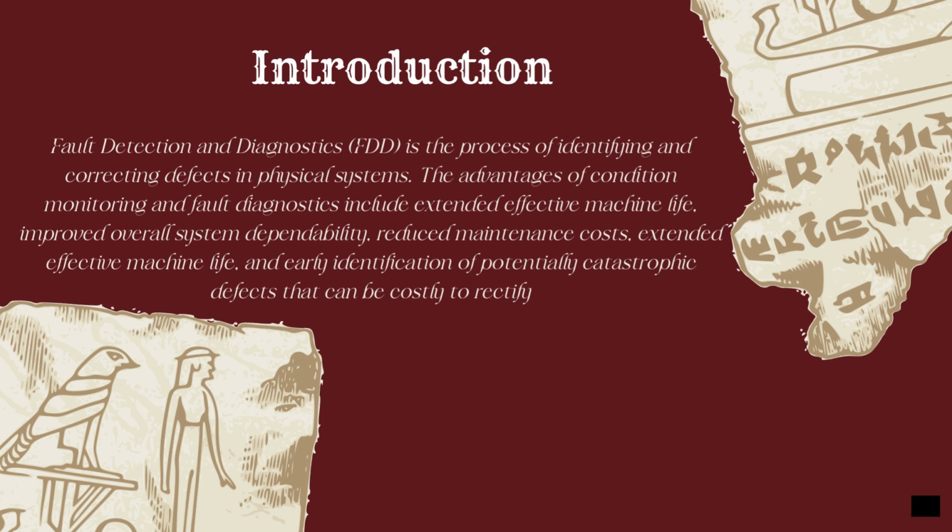Vibration analysis, oil analysis, temperature analysis, and ultrasound analysis are the fundamental condition monitoring techniques. The advantages of condition monitoring and fault diagnostics include extended effective machine life, improved overall system dependability, reduced maintenance costs, and early identification of potentially catastrophic defects that can be costly to rectify.